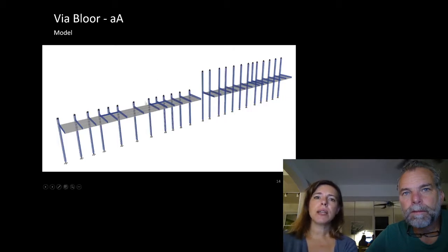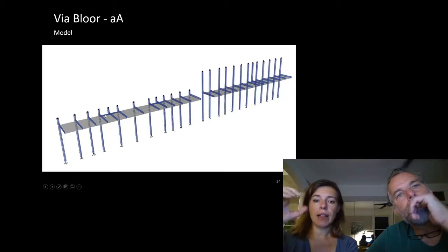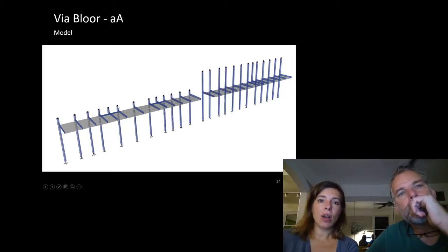So this is kind of what we ended up with. There were a few different conditions for this, one with really tall columns and one with really short columns. And where they had doorways, so you can imagine a doorway right here, we couldn't bring our column down, so I had to add a torsion element that connected into these columns.